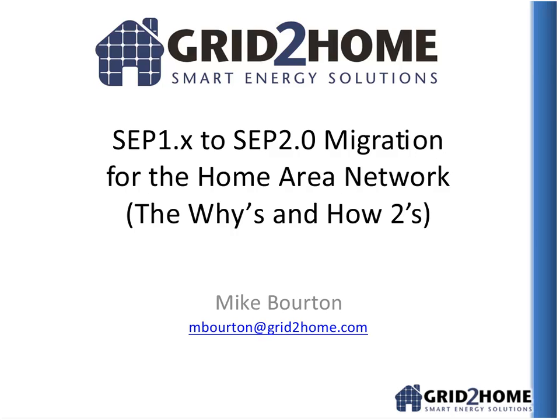We were not there a few years ago when we had highly proprietary protocols working in home area networks, using network protocols that were also vertically locked down, so that the semantic layer, the protocol in between, and the PHY/MAC layer were all cobbled together. It works great if you have a single vendor solution, but in the smart grid, what we're talking about going forward is a multi-vendor environment. So in that environment, it's really important to have open standards, not just in the semantic layer, but in all the layers, so that they can be very modular in the architecture and can fit in.